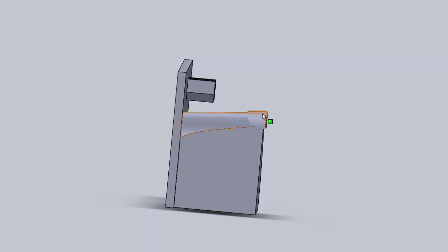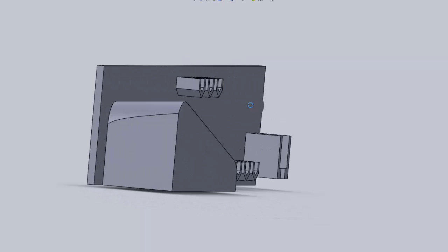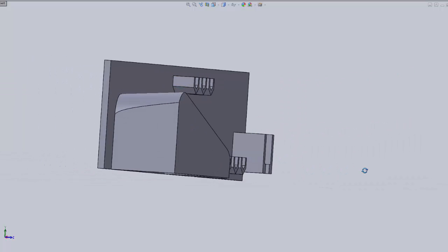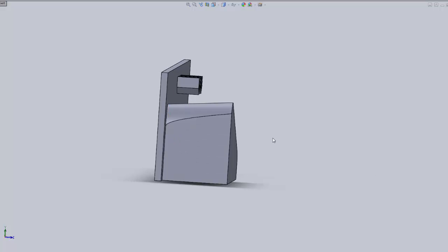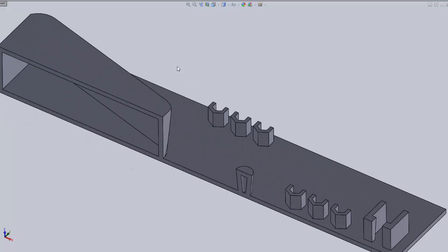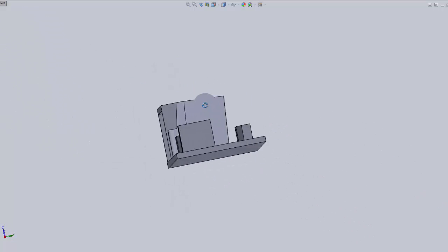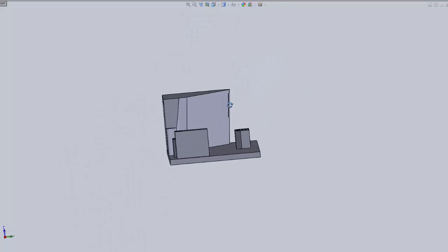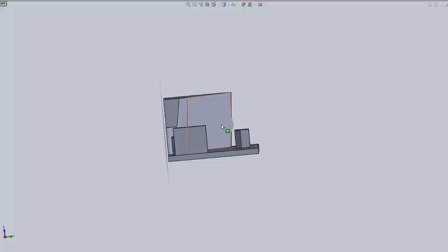What I did instead is I made it simply a slant, so that if I had made a lip, that lip may have been broken off, but I slanted that surface and this surface and this surface down here, which made it impossible to use a simple mold that would go left right this way. So it ends up being possible to go left right this way. Well, there we go. Something like that. So down this way and up that way.